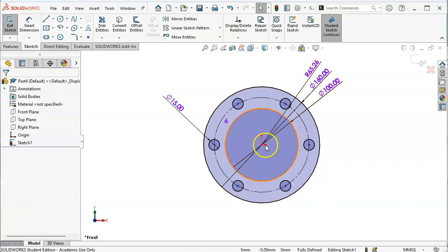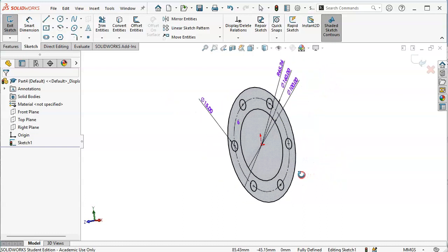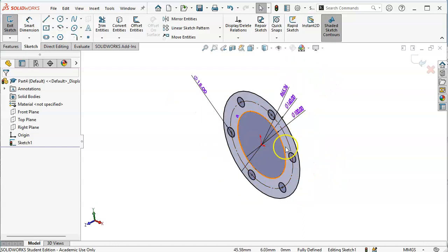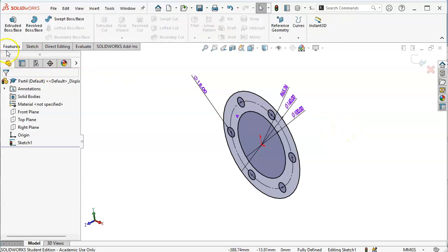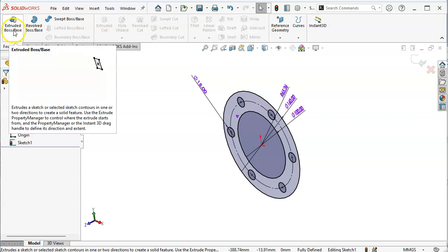All right, and the only place where that 7th point is an issue is when we get over to our hole wizard and we're doing predefined library of geometry. A lot of times that will add another hole instance that we don't necessarily want.